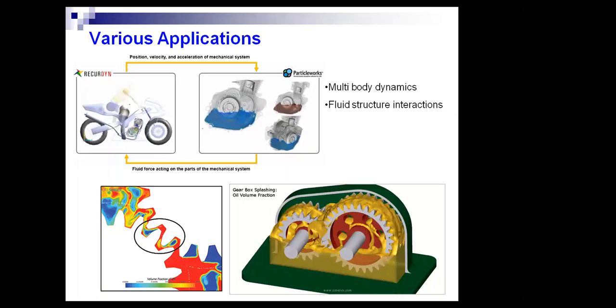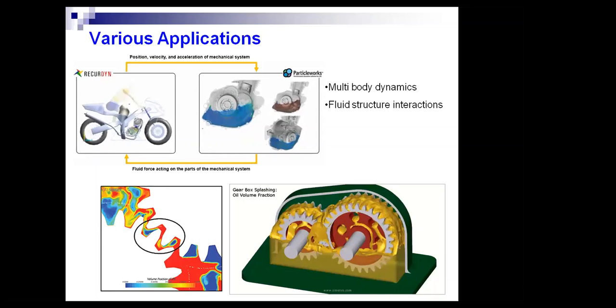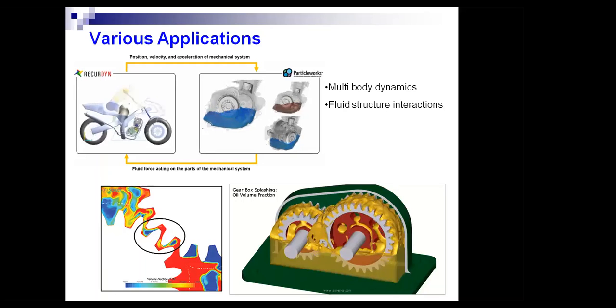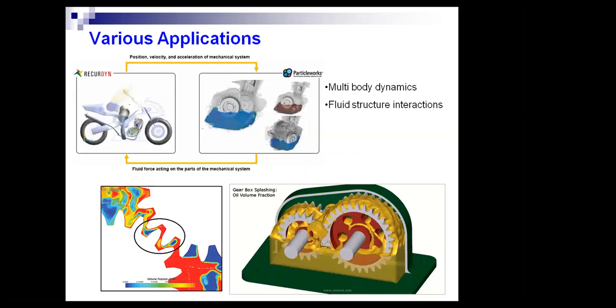If the hole is not provided in the gear, this lubricant flow will not happen through that hole. Thereby, the bearings mounted just below the gears will not get sufficient lubrication. In that condition, the contact components, the bearing rollers, rolling elements and the raceways will heat up faster, and it will reduce the life of the bearing.